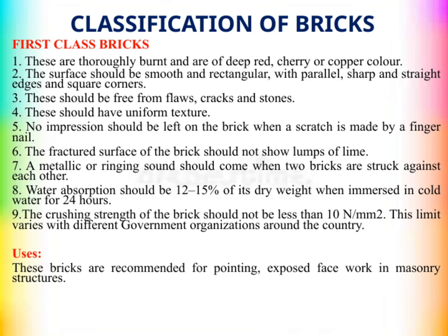It's also important that these bricks are free from flaws, cracks, or stones, as defects can weaken the structure. They should have a consistent, uniform texture throughout, which indicates good manufacturing quality. When you scratch the brick with your fingernail, no impression should be left, meaning the surface is hard and well fired. Another point to check is the fractured surface. It shouldn't show lumps of lime, which can suggest incomplete burning or poor quality.